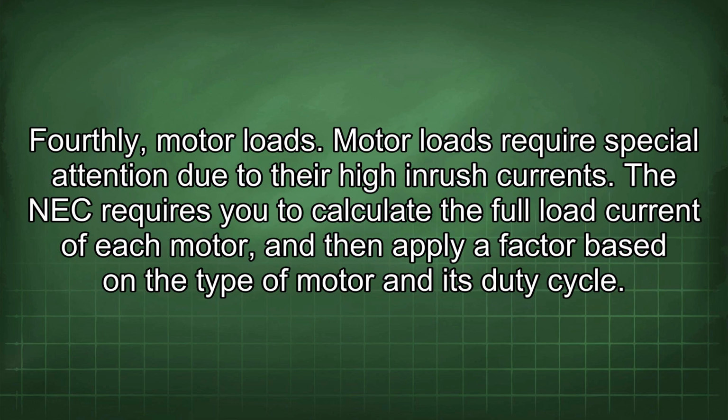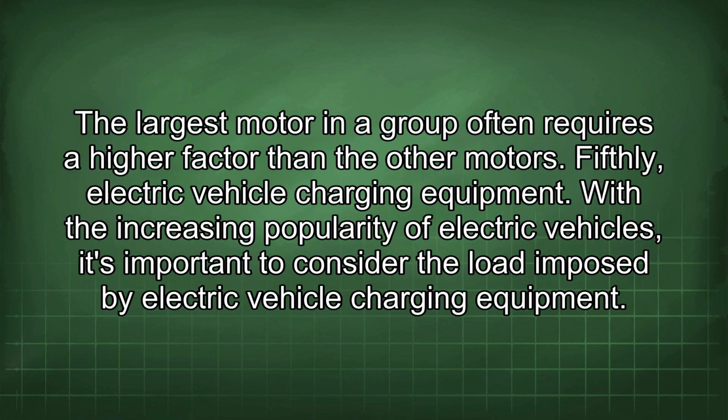Fourthly, motor loads. Motor loads require special attention due to their high inrush currents. The NEC requires you to calculate the full load current of each motor, and then apply a factor based on the type of motor and its duty cycle. The largest motor in a group often requires a higher factor than the other motors.